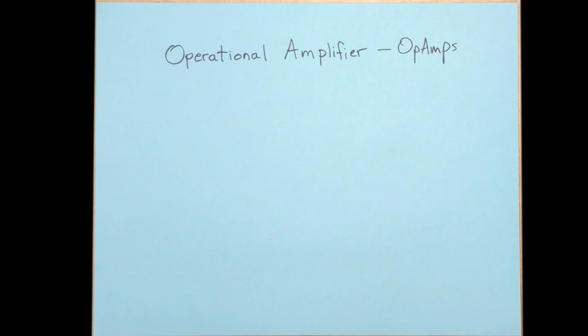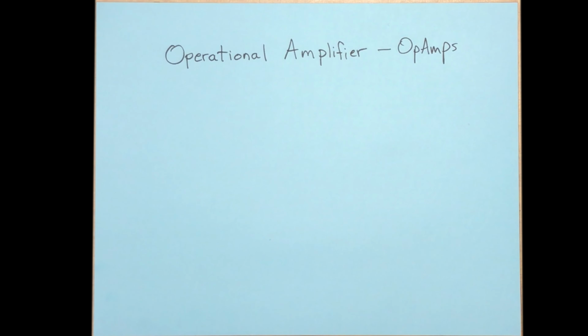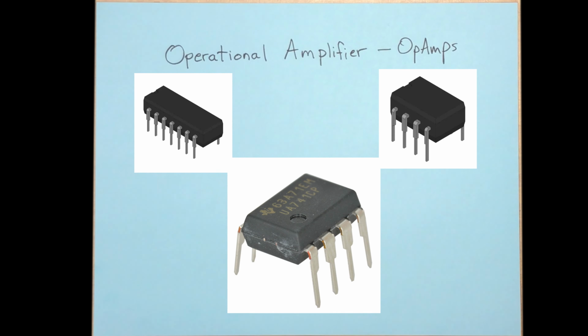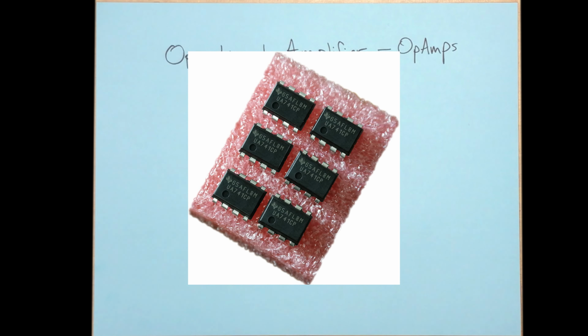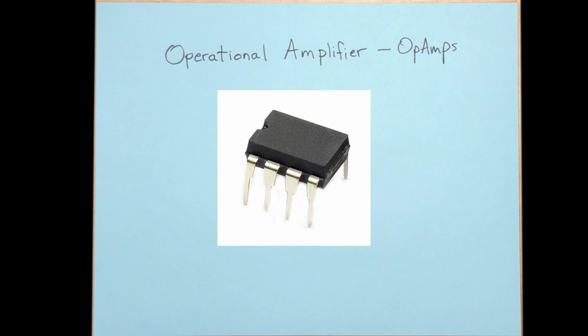All right, so what does an operational amplifier look like? Let's begin with that. An operational amplifier is an integrated circuit. It comes in a lot of different shapes. You can buy chips that have 4 operational amplifiers or 2 operational amplifiers or 1 operational amplifier. This one here is a 741 chip, and it has 8 pins, and it's got 1 operational amplifier inside of it. And you'll notice the chip has 4 pins on each side, and it usually fits down into a socket. But the pins have different purposes, and you need to know how the pins are numbered here.